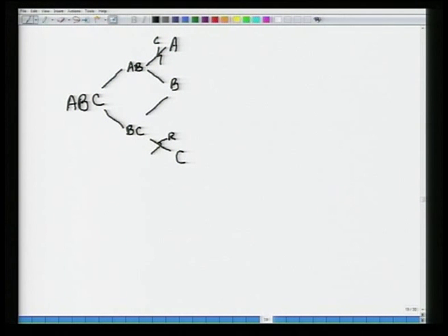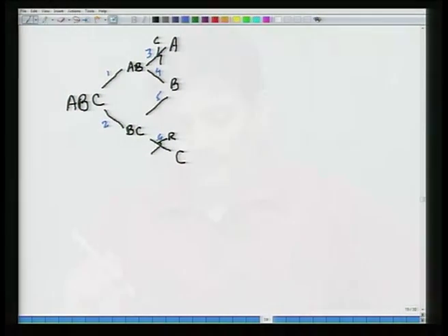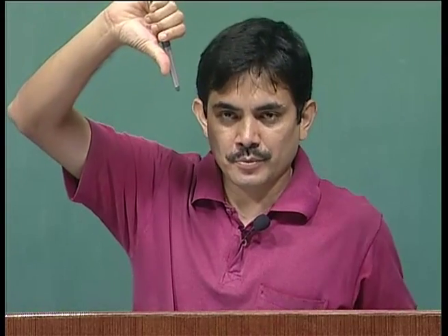This is actually a state task network representation and it is not necessary to know the details, but I just want to show you how to synthesize these complex column configurations in a systematic way. So, let me call these 1, 2, 3, 4, 5, 6. So, we have got column sections, all right. Each of the column sections will be getting a liquid stream from the top and a vapor stream from the bottom, and these will be contacted on the trays that are there in the column section, all right.